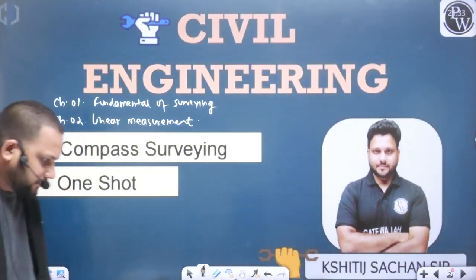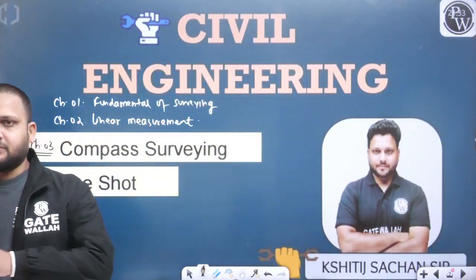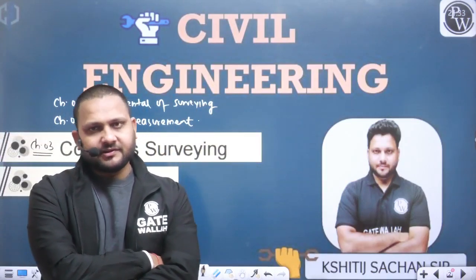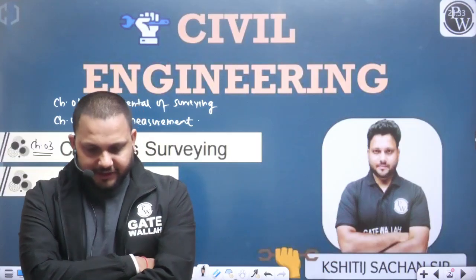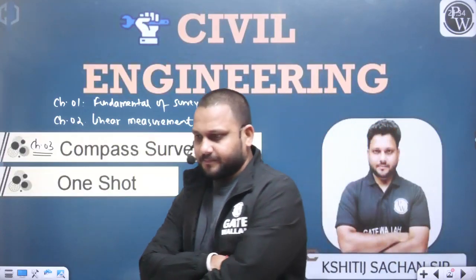As we know, in the case of surveying, in this subject we have to measure basically 2 things. One is distance and another is angle, that we have discussed. So we need to measure the horizontal distance and the vertical distance. Similarly, we need to measure the horizontal angle and the vertical angle. With the help of these measurements, we can define the relative position of a point, and with the help of that relative position, we can prepare the plan or map.